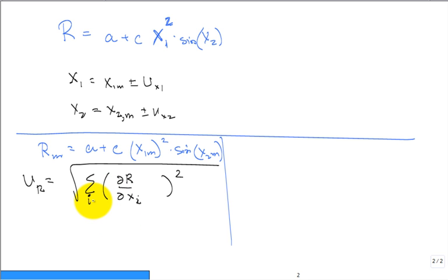And after we take the derivative of that response with each of the inputs, I'm going to have to evaluate it somewhere. Evaluate it at the mean, just like we evaluated the response at all the means of the inputs. You evaluate the derivative at the mean. And then you multiply that by what? The uncertainty in each of those inputs, x of i.